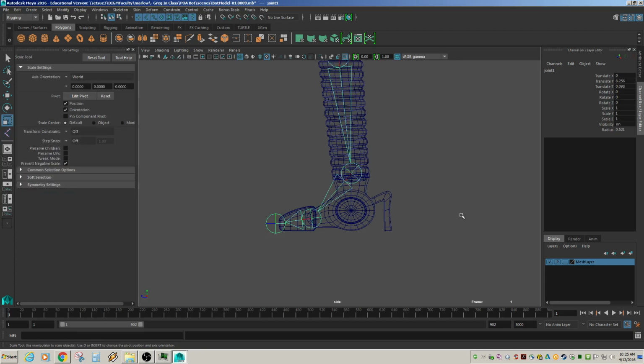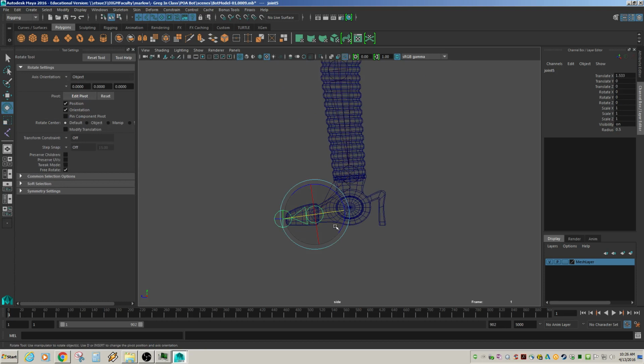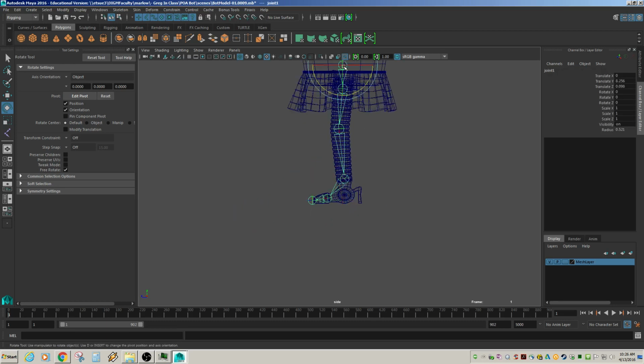And then if I hit enter, you'll see that that's what I have now for my leg. Right? And you'll see what I was talking about, that now if I rotate it like this, I can see how the toe moves, versus if I didn't have that one, although the toe is rotating, you can't really see an example of it. So it's more just for visuals for me. And so that's my entire chain.